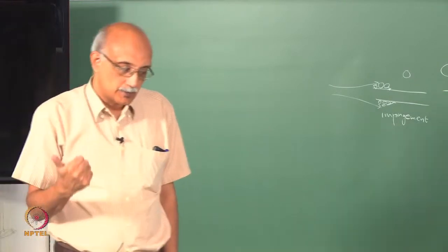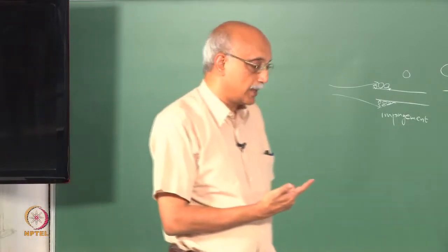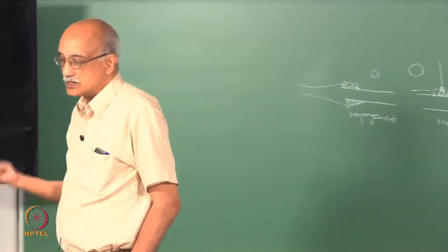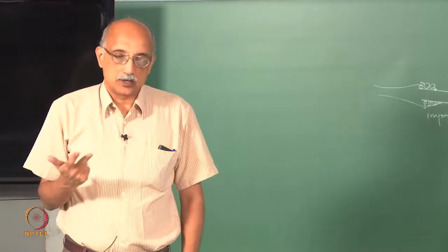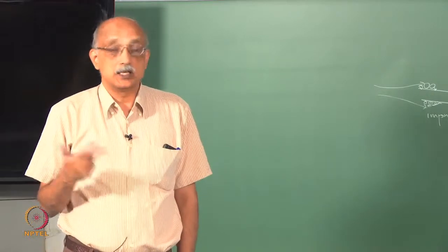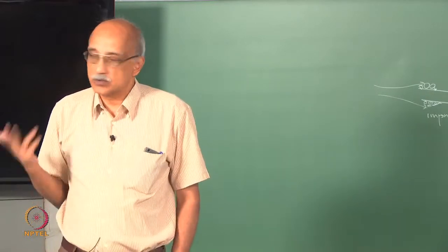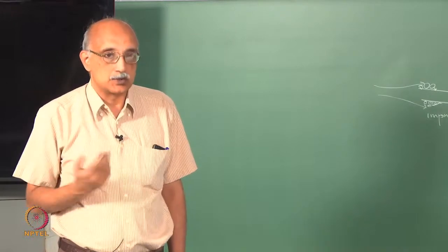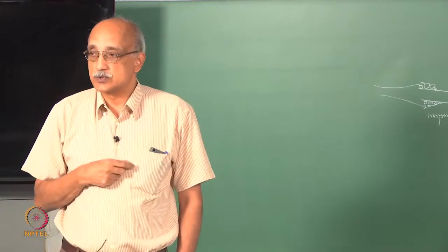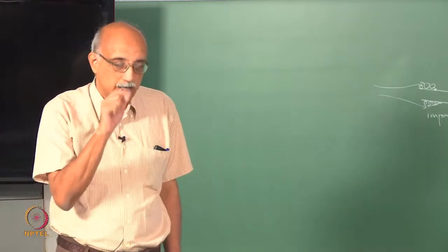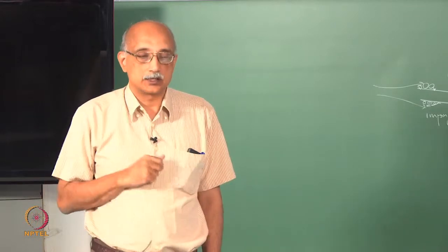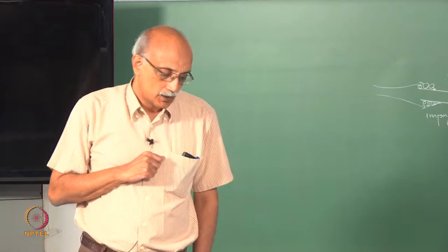So, you go from naked eye inspection to optical microscopes to electron microscopes, and of course, there are many variations of this. SEM has a resolution of a few tens of nanometers. If you want to get even better, you go to a TEM, which can give you a few nanometers resolution. There are also AFMs, atomic force microscopes, which can again give you nano dimensional detail in 3 dimensions because of the way that an atomic force microscope works.